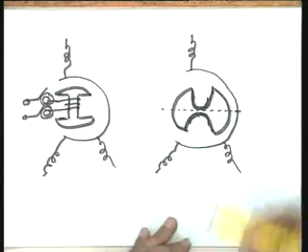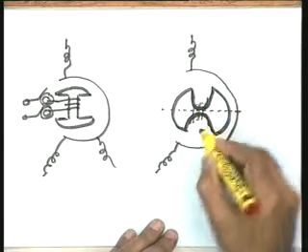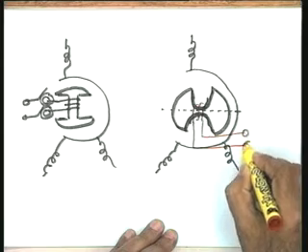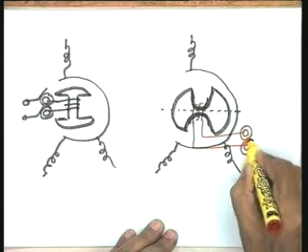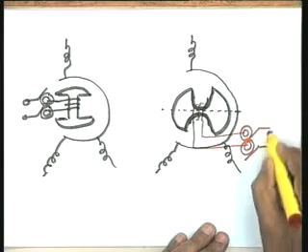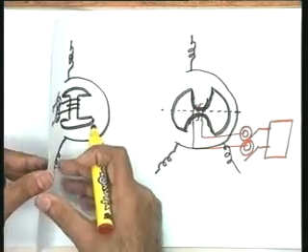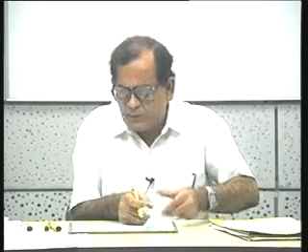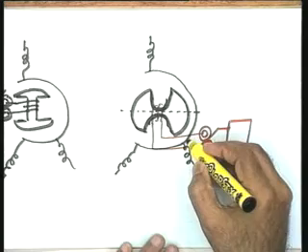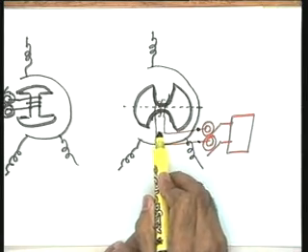The reason being that the output of this particular rotor is going to a signal conditioning device, an amplifier maybe, or a demodulator. I really want that this particular device should see a constant impedance.